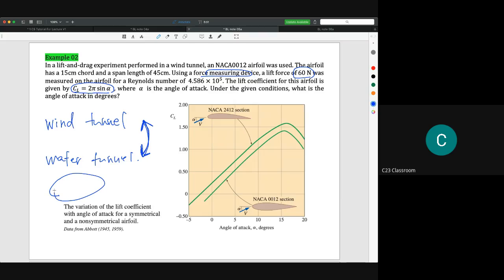So you have a big model. Maybe you will have a boundary layer here. When you scale it down, maybe the boundary layer will reduce a little bit. So the ratio of this boundary layer compared with the size of the object can be acceptable. But if you are using a small object, the boundary layer will give you the same thickness. Even if you use a different size of object, the boundary layer will remain the same. That's the effect of the boundary layer.